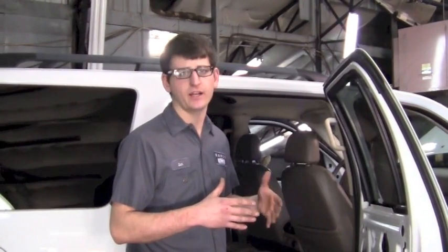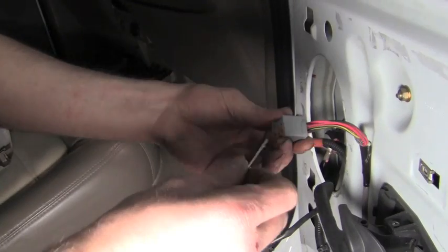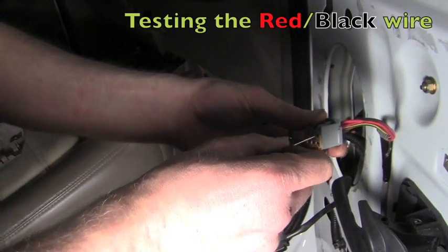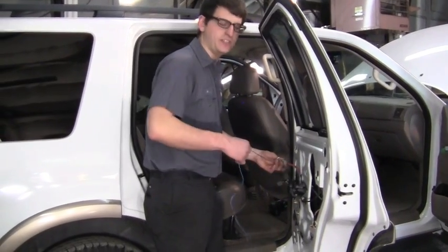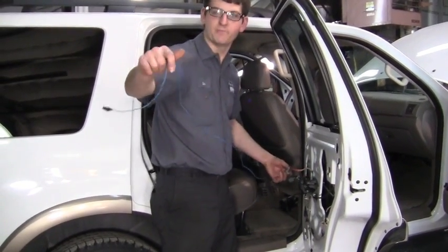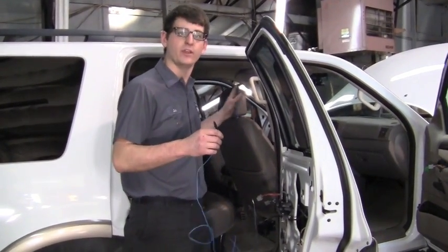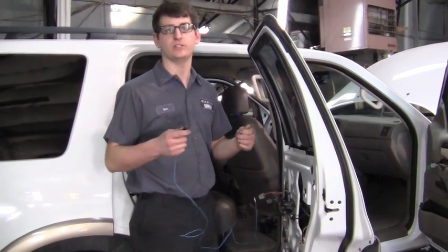Now keep in mind that a continuity check will only let us know if there's an open in the circuit. It will not test for high resistance. At the right rear switch, what I'm going to do is take a back probing pin and plug that into the connector on the red and black wire. As you can see, this wire is really long, that way I can reach my voltmeter. Then what I'm going to have to do is back probe from the other side with another wire and connect both leads to my voltmeter so I can do a continuity check.